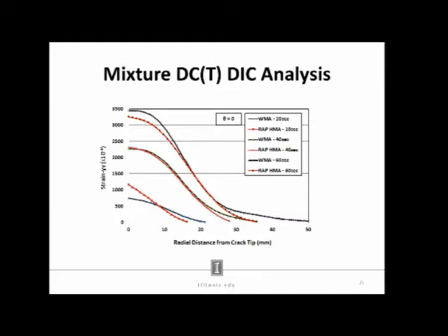One thing I do want to note, though, is that once you get probably beyond 1,000 microstrain, you're probably not dealing with real material behavior. That's just pure separation in those regions. But you can definitely tell that with the warm mix asphalt, you're seeing an increased amount of deformation in the material at every single time interval, as compared to the 45% RAP.